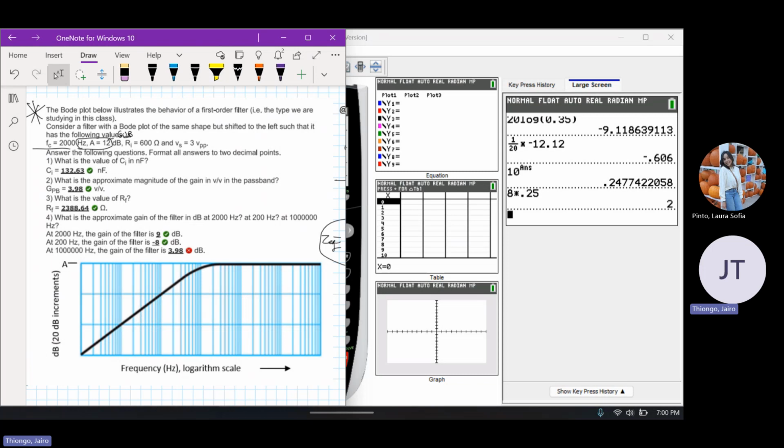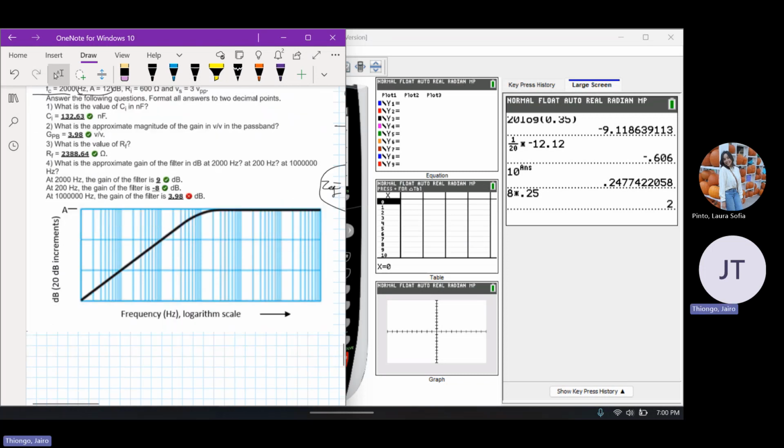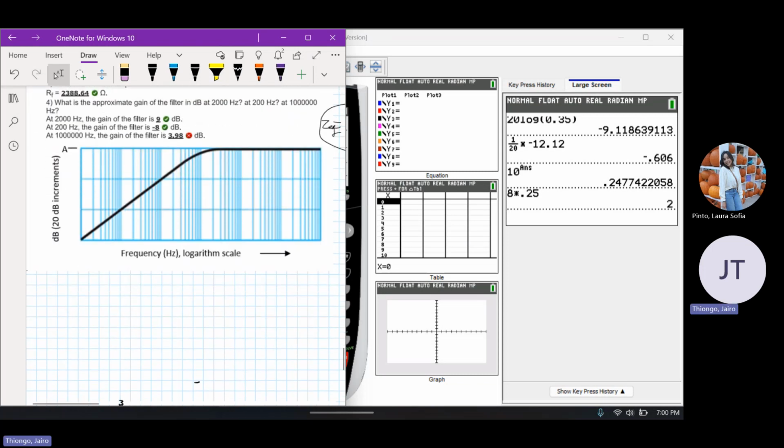So this is the Bode plot. Looking at it, you might be confused, but just think of it as a representation of what the filter does. This is the attenuation zone, where we have the slanting attenuation. Here's the cutoff frequency, and from here going forward, it's the passband.